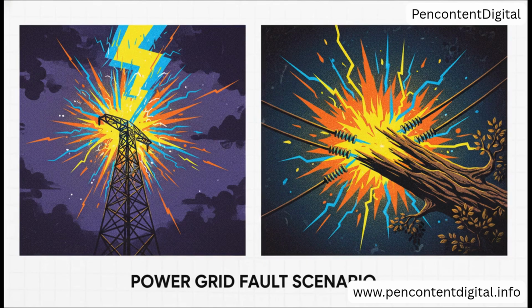That's where short-circuit analysis comes in. Engineers can simulate severe events, single line-to-ground faults, line-to-line faults, or those massive three-phase faults. They blast these intense bursts of virtual fault current through the model just to see if the protective relays will trip in time or if the whole thing is going to go down like dominoes.